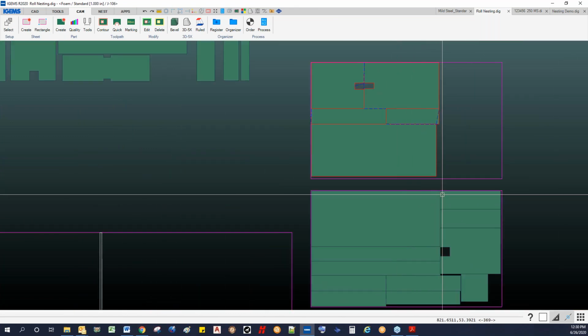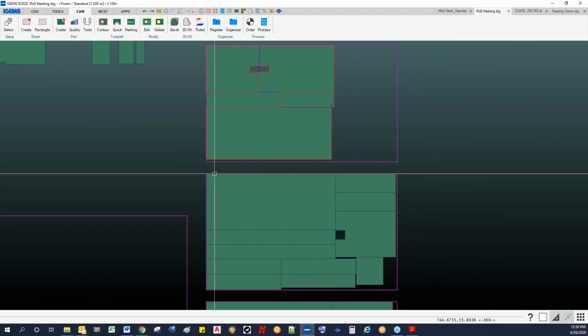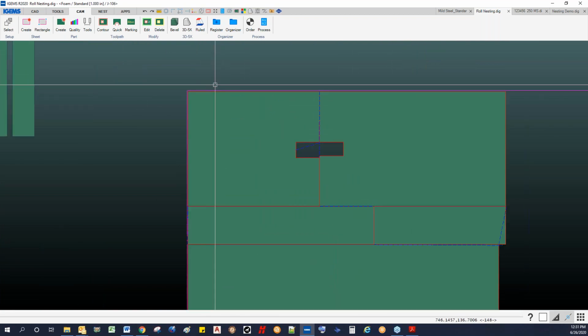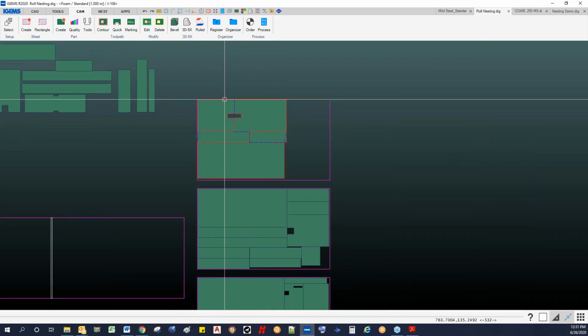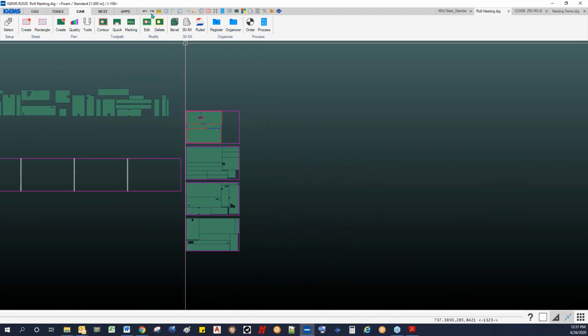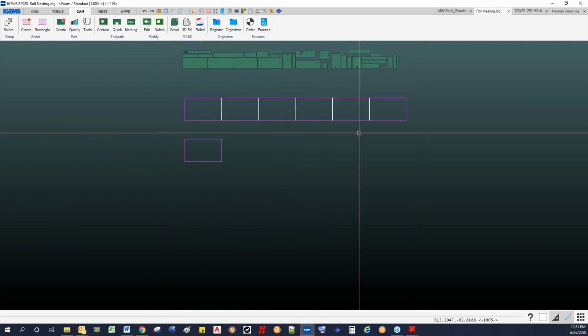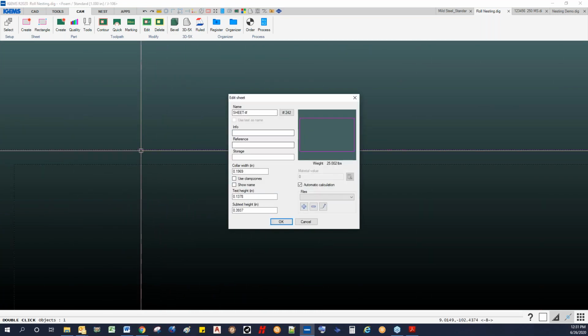So this one here, we've got a little bit of a gap here. If you can put your material on there because you have a fixture, or like that video I was showing you where it has a guide that's going to guide that material in, you can actually nest it right up against the edge of that sheet of material and use that as your raw edge and not have to do this cut that's along there. So if you want to do something like that, then we would just change our border on our sheet. So rather than having a border on here, you can click on here and tell it not to use the collar.